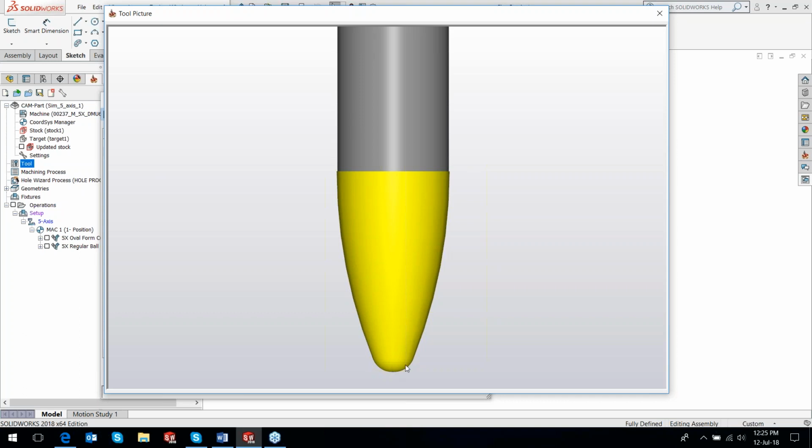If you give a pretty large tilt angle, there is always a danger of this portion coming in contact with the material, and that will ruin your concept of going fast. If you give a pretty small tilt angle or no tilt angle at all, again, you're in danger that this portion is going to be in contact with the material. If the shank is also of the same diameter, there's a possibility that the shank could start rubbing against the finished area.